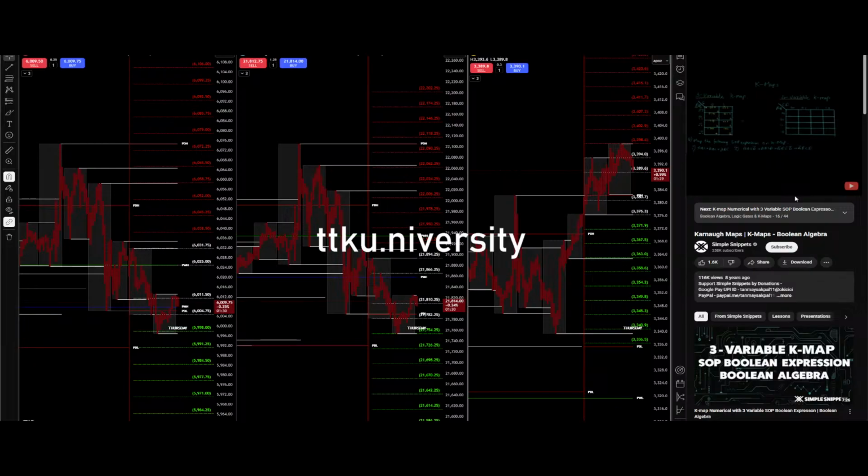So now let's take an example of a Boolean expression. Here you can see I have written question 1, wherein we have to map the following SOP expressions on the K-map. So now we know SOP is associated with the number 1, that is, all the variables having 0 value need to be complemented and converted to 1 1 1. So the value of this cell would be A complement, B complement and C complement, since all the variable values are 0.